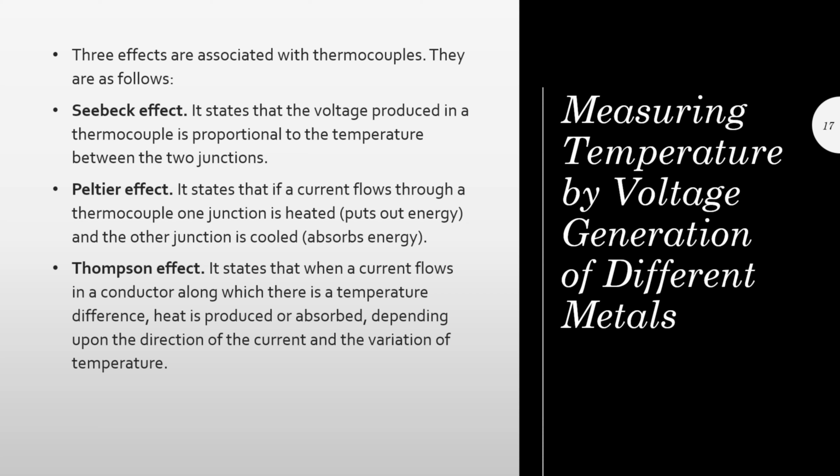The first principle, the Seebeck effect, says that the voltage produced in a thermocouple is proportional to the temperature difference between the two junctions. So if there is a temperature difference between two junctions, a voltage will be produced.